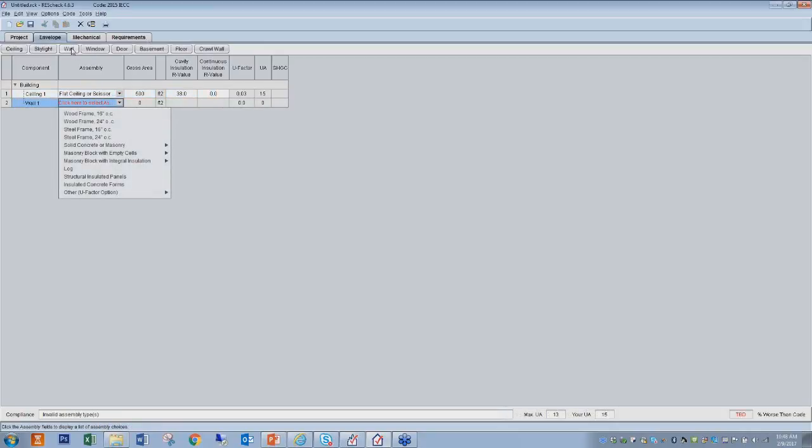Walls. I have those 3 exterior walls. If they're all the same type of assembly, construction, I can total them all up, one line item. So let's just put in 16-inch on center. I'm totaling up all my exterior walls. This is the opaque area. Let's say I have 1,200 square feet. That includes the windows and doors that are in those walls. My insulation value. And it recalculated the U factor. So you'll see the U factor column there, and it shows 0.06.